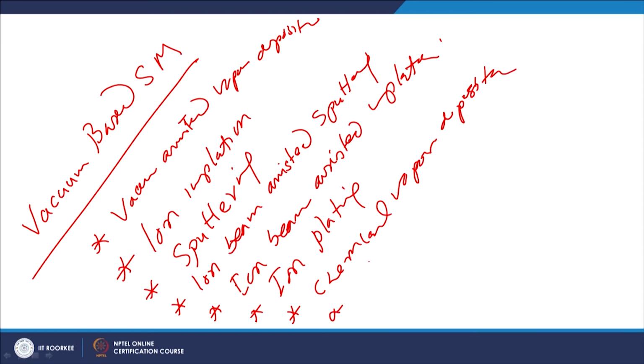All these processes where vapors are used, which are made available through the evaporation of the metal, can be ionized, or those vapors are accelerated and applied onto the surface of the substrate so that coatings can be formed on the surface of the substrate, and subsequently diffusion at a higher temperature will facilitate the compositional modification of surface and near surface layers.